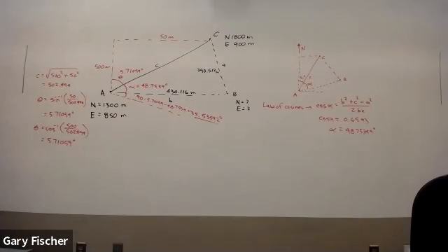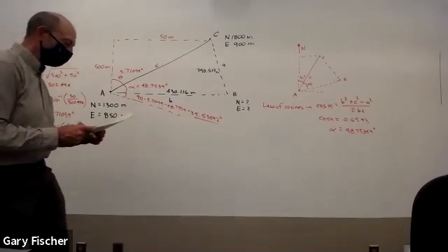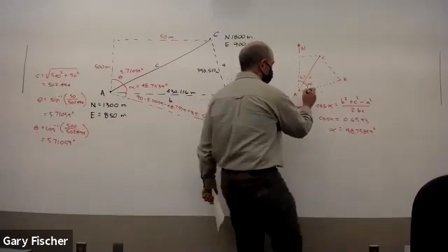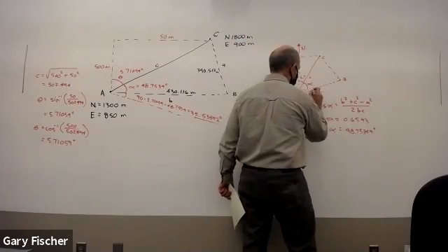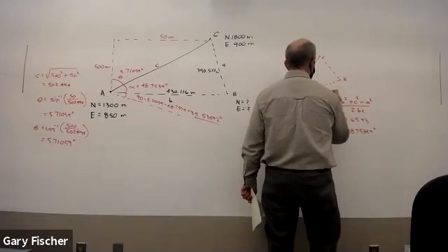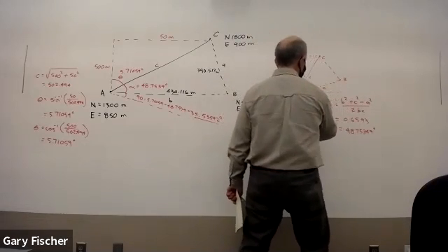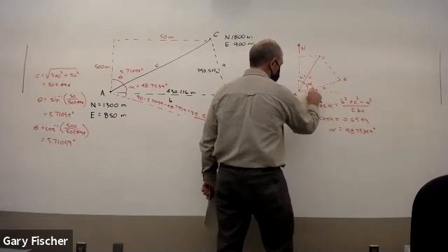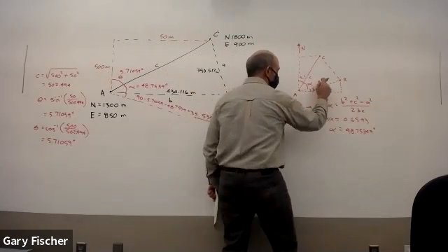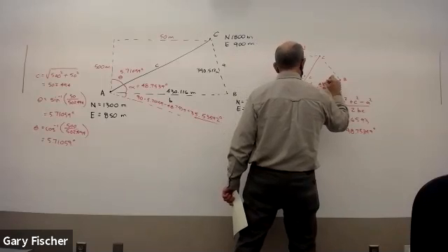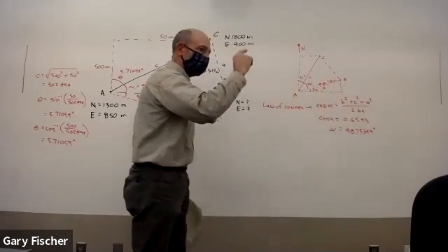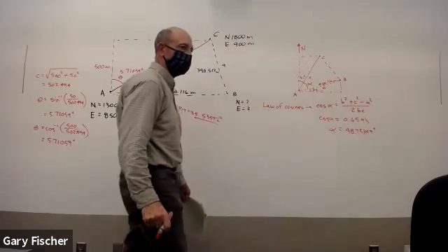Okay, why do we care about that? Because in our little diagram here, we've identified this angle, alpha. Then we got this, which was 35 point blah, blah, blah degrees. When we project this out, it runs along the east-west direction, because this is the north-south, and we've figured out this is a right angle, so we have a right angle triangle to point B. We know this angle and we know the length of this line, 430.116 meters. We can then calculate this horizontal distance, which would give us our easting, and this vertical distance, which would give us our northing at that point.